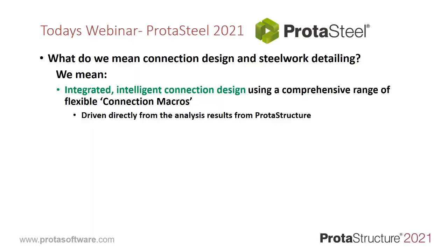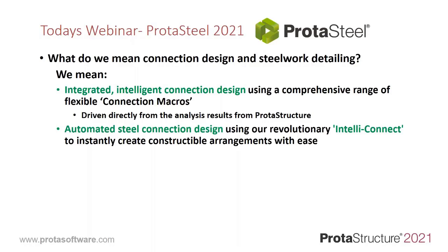We're talking about modules of the same program, which are tightly integrated. So once you're done with your ProtaStructure analysis, the whole model which you have created painstakingly is transferred to ProtaSteel. And you don't have to remake your steel model once you're in ProtaSteel. It's already there. All you now have to do is detail the steel work.